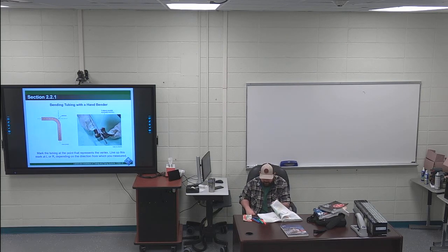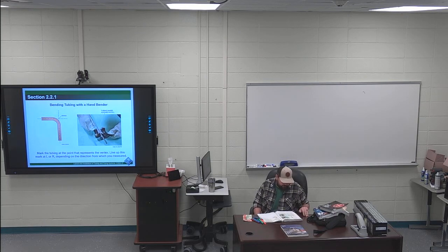Step 5 goes into page 26. Right after where you see spring back, I've got the rest of the step highlighted. Harder materials tend to spring back very slightly towards straight, therefore the bend may need to continue 2 or 3 degrees past the 0 and 90 degree marks.